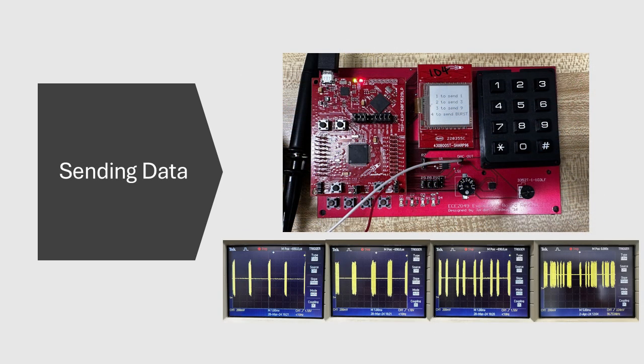We configured our microcontroller to send information in 4 different modes with the click of one of the 4 buttons on the board. Pressing the first button would send the number 1 in 8 bits, pressing the second would send the number 3, and pressing the third would send the number 9, as can be seen in the first 3 oscilloscope graphs. In the final oscilloscope graph, we see when the 4th button is pressed, enabling burst mode, which sends varying 16-bit numbers, simulating real-world use, where multiple pieces of information are sent at once.